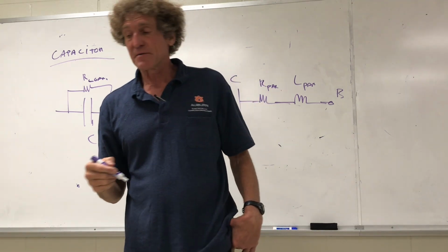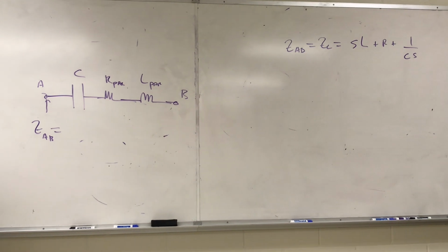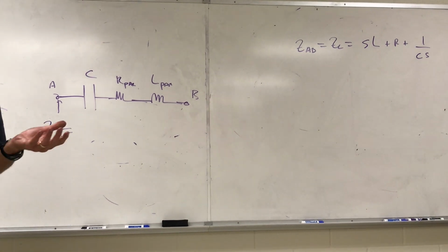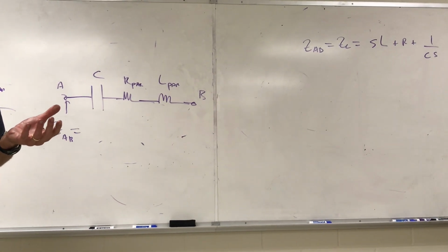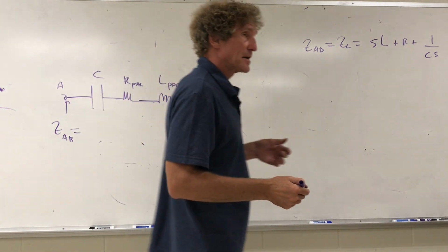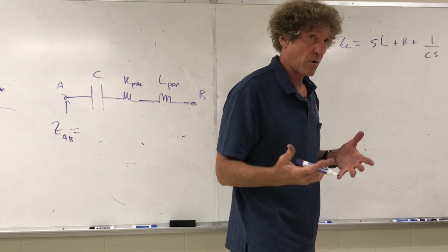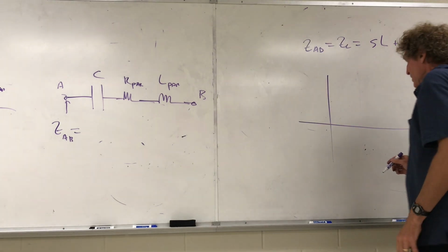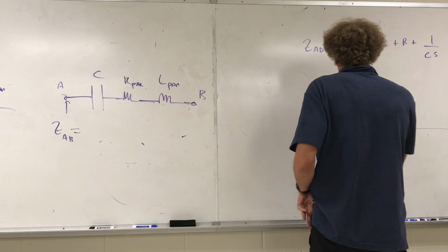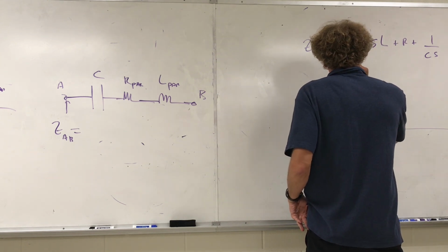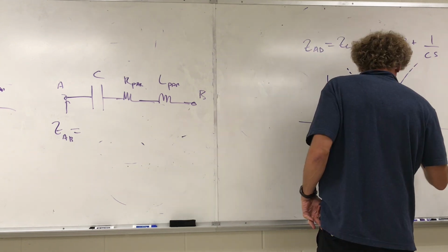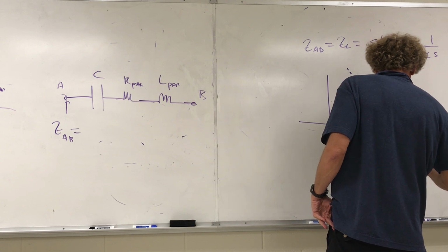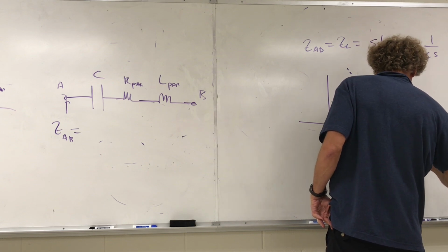What is the impedance of a capacitor? And you'll notice I got rid of this leakage resistance. What's the impedance of a capacitor at DC? Think about it. It would be infinite. Technically, he was right. If it's an electrolytic, it would be R. And here's the plot you get. We can get to the resonant frequency. What happens is you're going to get something, and the self-resonant frequency is going to be 1 over 2 pi square root of LC.